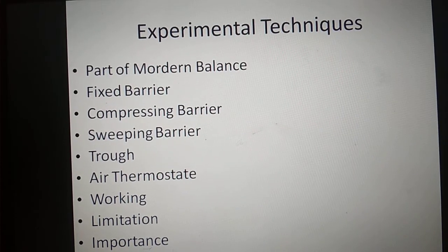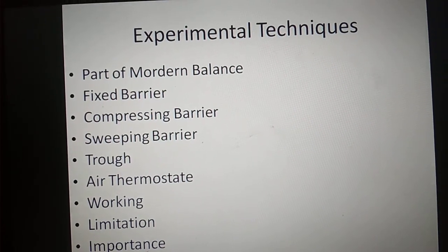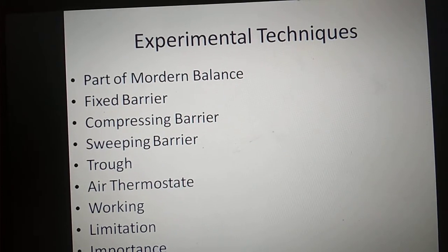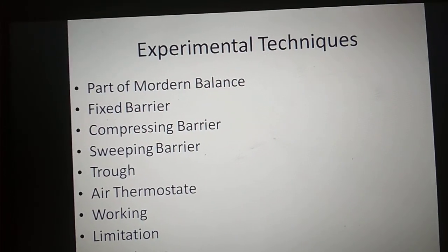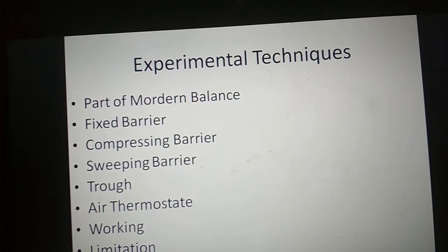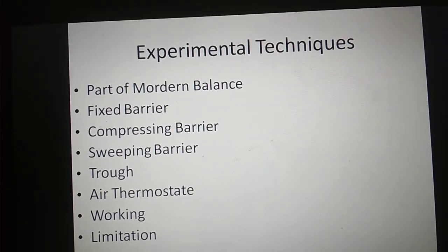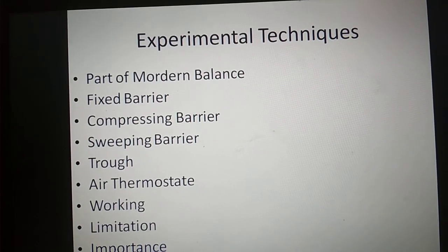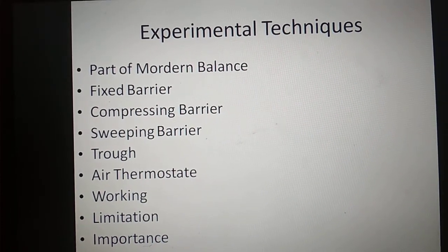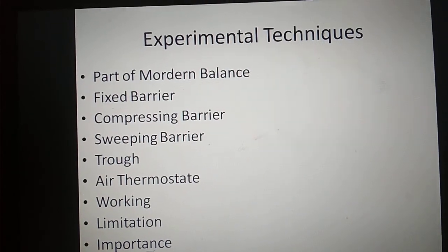The surface film exerts a surface pressure on the float, pushing it backward. The torsion wire attached to a calibrated circular scale is twisted until the float is returned to its original position. The required force divided by the length of the float is the surface pressure.